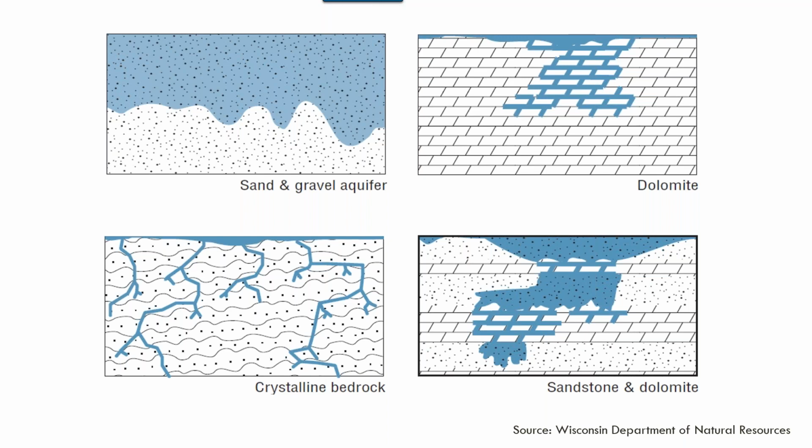And the sandstone and dolomite example together, these are very much simplifications, but you can see how water can move through some sandstones, but it's usually not just a sandstone, but several different geologic units of different permeabilities, and so that dictates how the water might move through and get to a lower unit. There could be a shale in there that stops it all, and then it all runs horizontal from that point. And the other thing to note here is these all show bedrock as a flat layer, and rarely is bedrock flat. I mean, these units are angled.